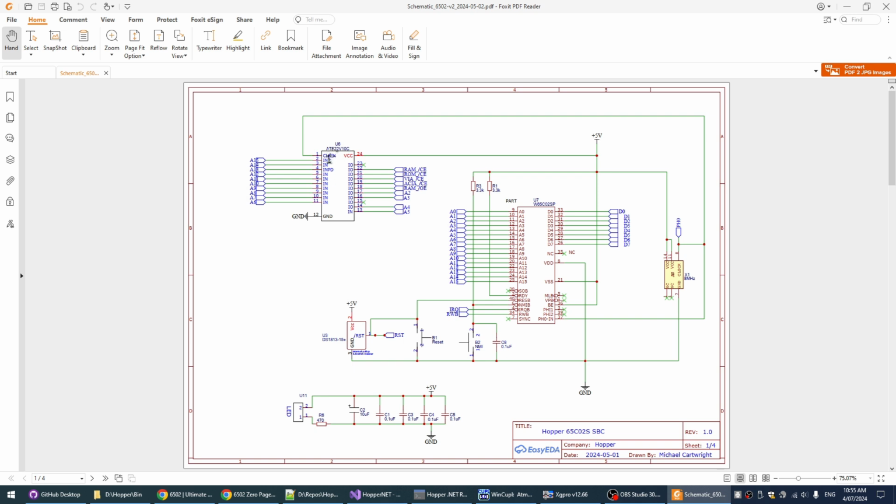And it mentions the Atmel 22V10 with 10 macro cells, but it applies just as much for the Lattice GAL 20V8. They're pin compatible. The 10 has 10 macro cells, the 8 has 8 macro cells, but the same program works in both of them. So you can do more with the 10. The 10 can be more granular if you wanted to, but I haven't taken advantage of that yet.